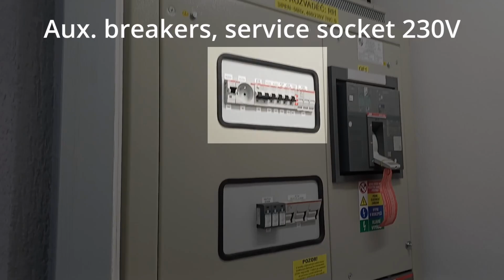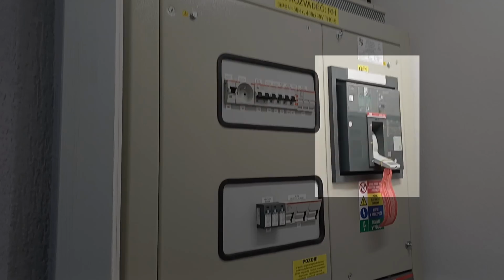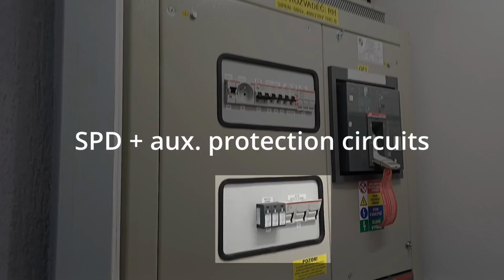These are smaller circuit breakers. They typically protect auxiliary or control circuits. And this is the main circuit breaker. This device protects the entire low voltage output of the transformer, and it can disconnect the whole system if needed. These sections contain protection and distribution elements. They are used to control and distribute power to individual feeders.